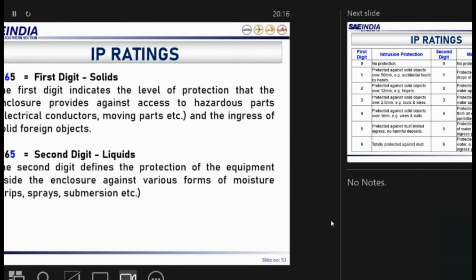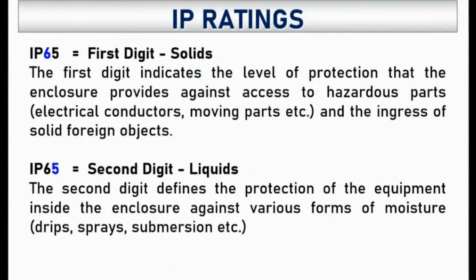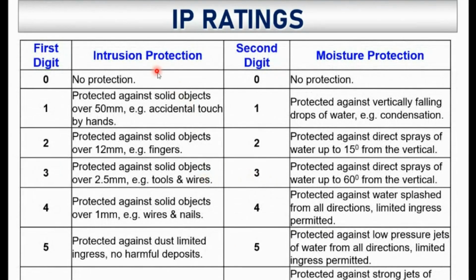Now maybe some other general information, the IP rating. Most of us are pretty familiar, but please also check the IP ratings before you buy or source your batteries and motors. And if you want to decode this information, the first digit represents the solid and the second digit represents the liquid protection.